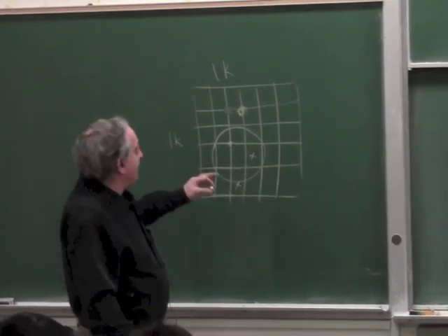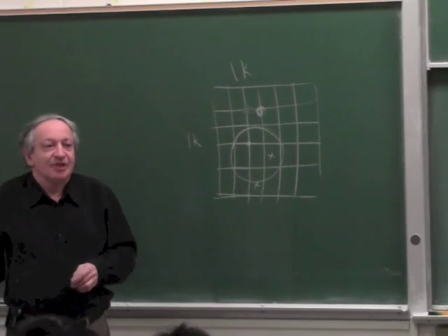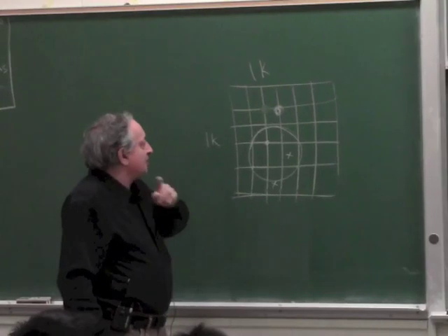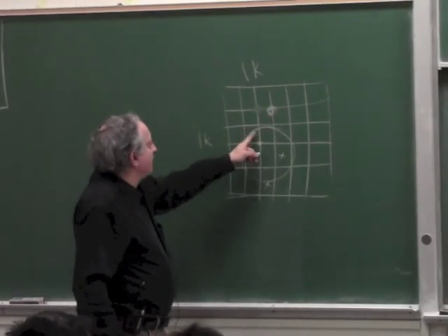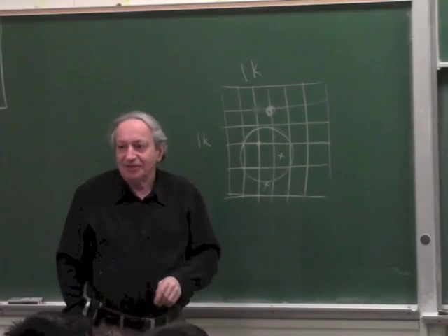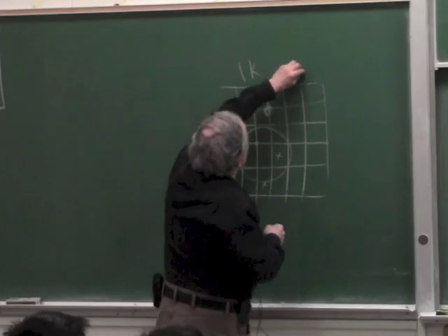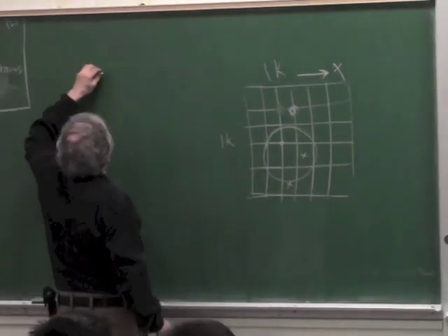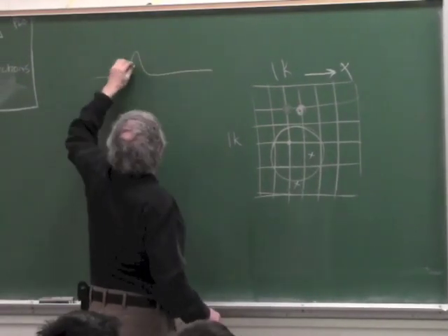But in a camera, it's even more important to use a big spot, because if you use a small spot, and we talked about early quantization, you can only have a resolution equal to the number of rows or the number of columns, right? If you use a small spot and the spot is moving in the X direction, you will get the following readout. The first time you'll get a readout like this, and you'll quantize it.